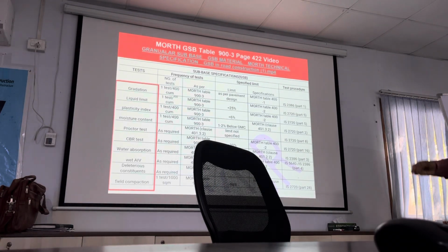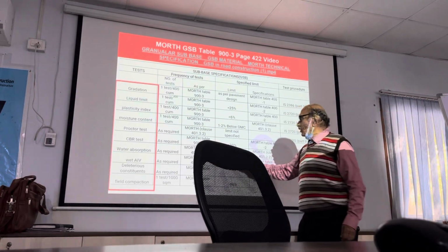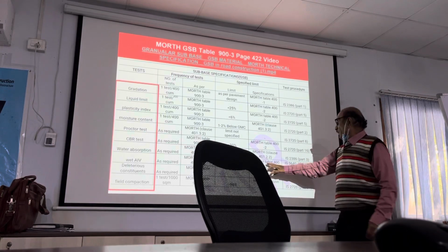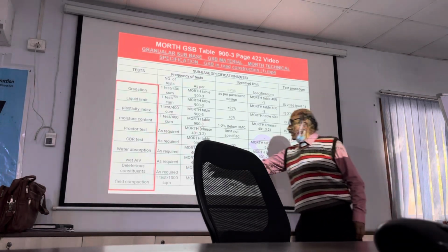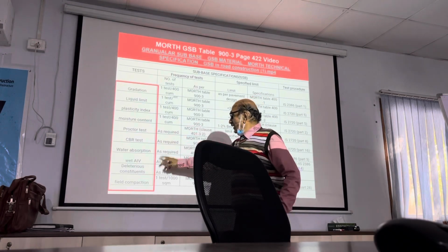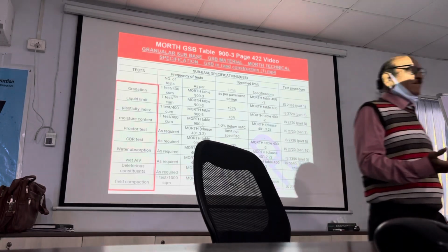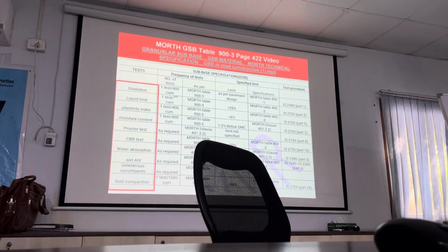There are 1000 tests. What is the limit? Aggregate impact value maximum. One test for this. Field compaction factor: one test per 1000 square meter. So all the frequencies are given. So kindly refer MORTH section 900.